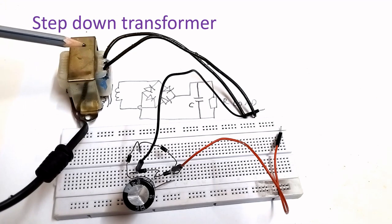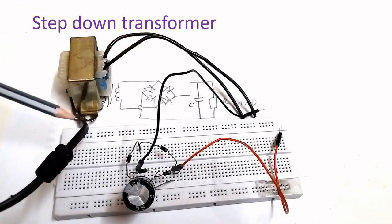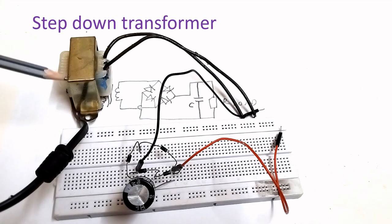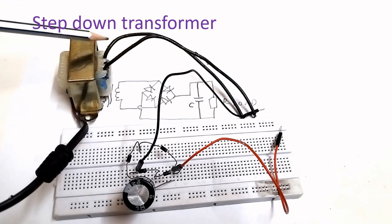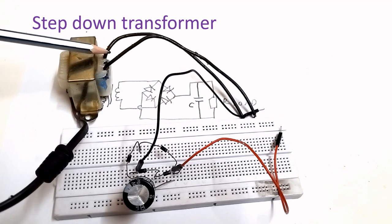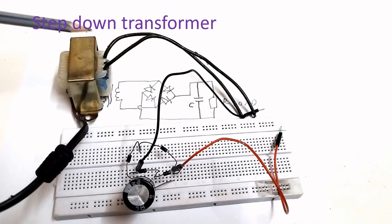The number of turns will be much higher than 230 because you have to cover the current needed, and sufficient impedance to the alternating current should be there. So the number of turns will be much higher, and on the higher voltage side, as the current is lower and the voltage is higher, you will use thinner insulated copper wire, and on the secondary side, as the current will be more and voltage will be lower, you use a thicker insulated copper wire. That is the usual pattern in step down transformers.